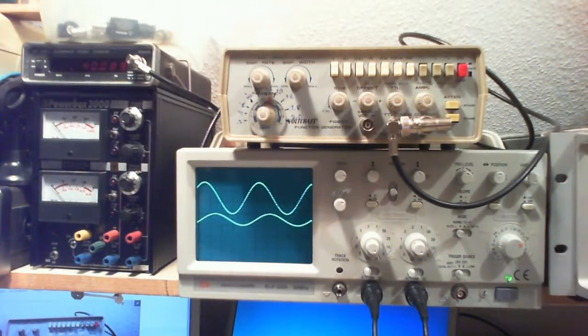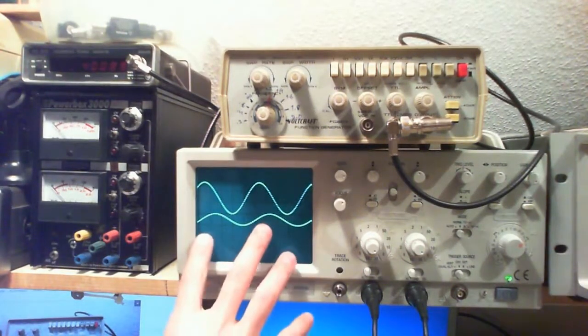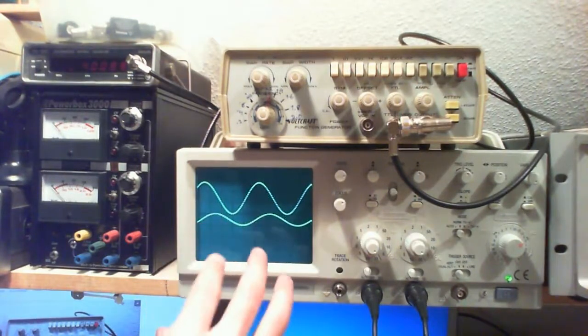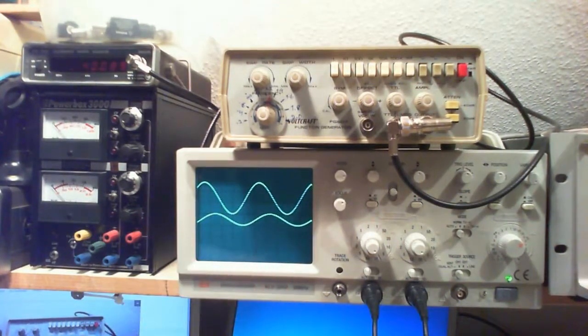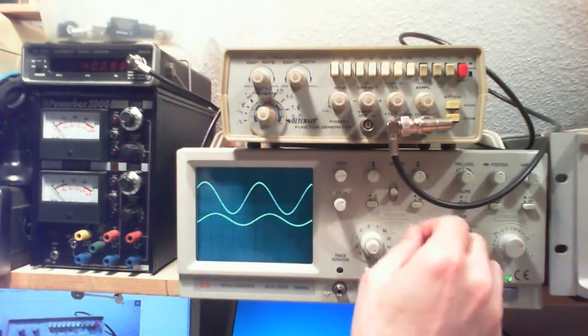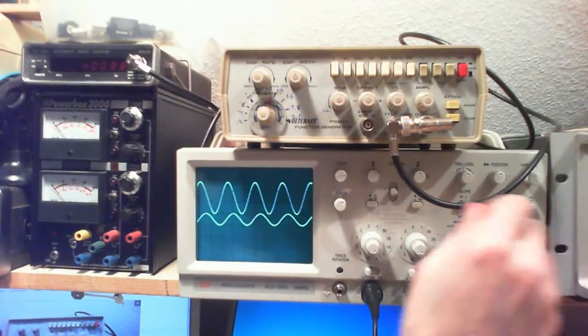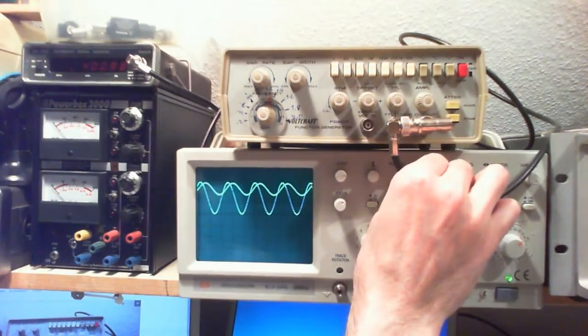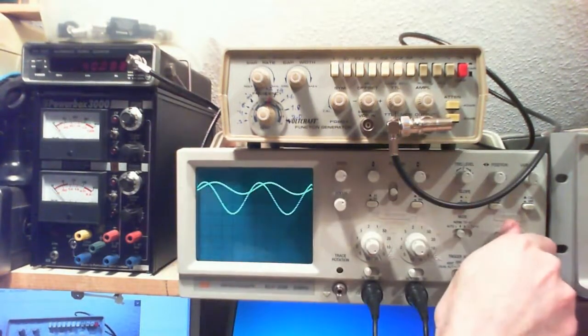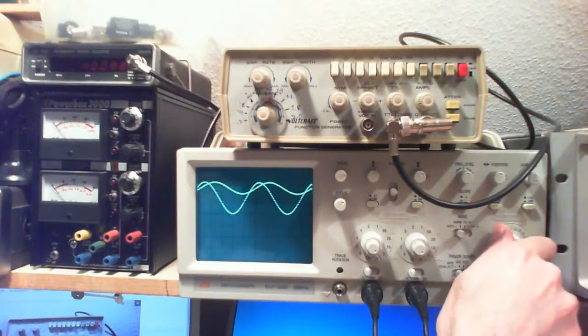Now I think that this phase shift is not going to change, meaning that the input is going to remain leading at least all the way up to 563 kilohertz, which is where the output starts to rise again. Okay, so let me go over here, and now this is my output, and you see that the input is still of course leading.